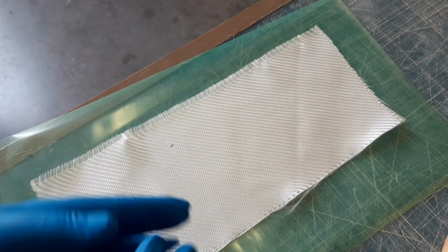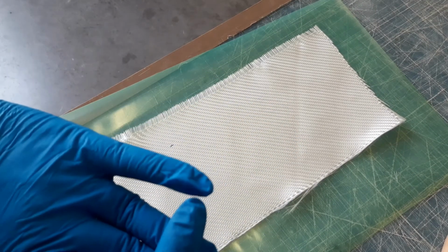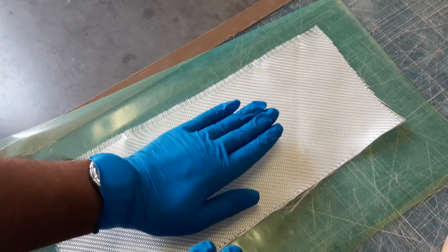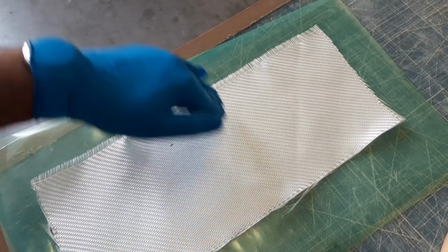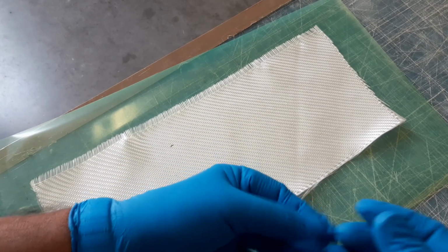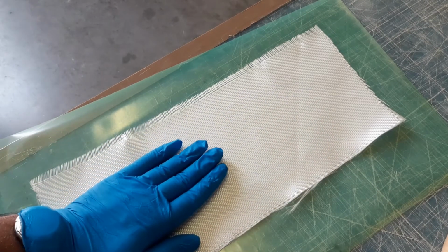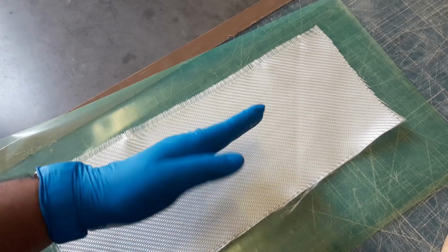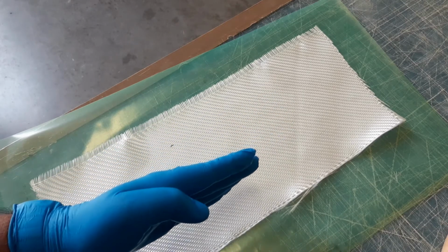Glass and carbon both are extremely rigid fibers. They don't stretch. The stretching is between the placement of the fibers with respect to each other. So these axis fibers and these axis fibers, they slide among themselves, and that is what I mean by stretching, and that is what I mean by shear in the cloth. This is not the shear of the fibers. This is the shear of the placed fibers between themselves.